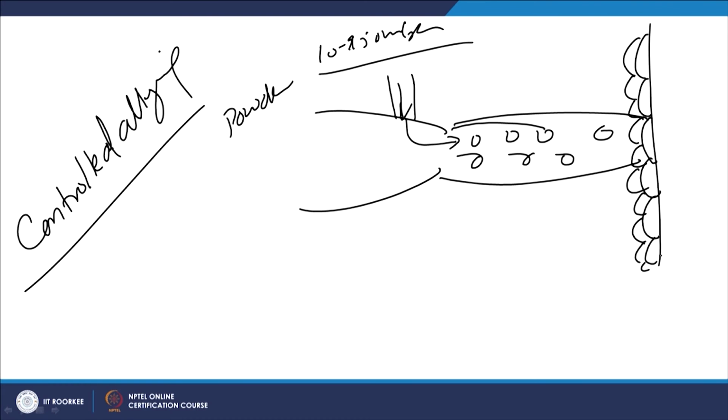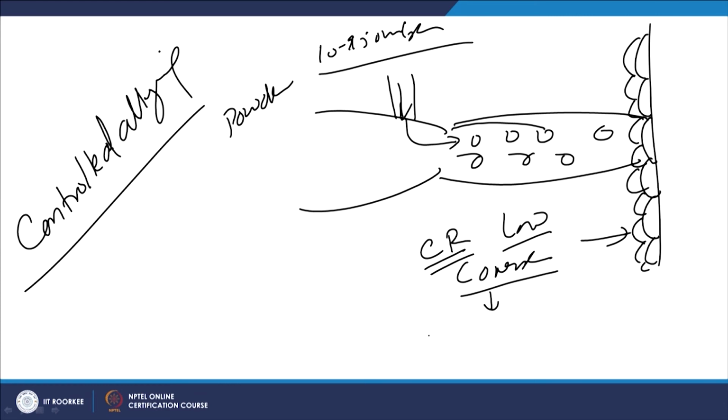Since the cooling rates experienced in flame spray coating are low, it offers a coarse grain structure. So, in order to improve the mechanical performance and the tribological performance with regard to wear resistance, it will be good if the hardness can be enhanced by refining the grain structure. Therefore, as per the material to be applied, we will choose a suitable refiner which can be added in the coating material, so that the structure can be refined.